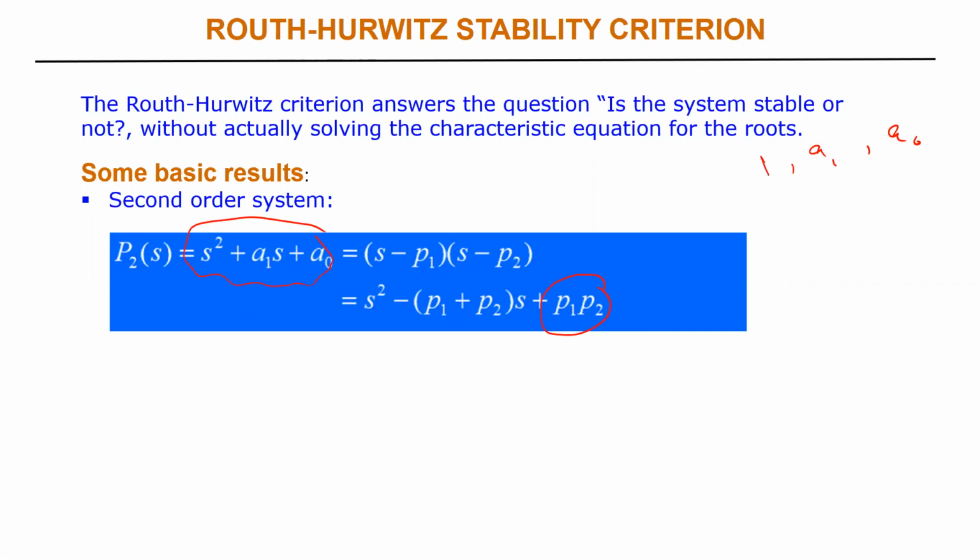It's an equation, so if they are negative, multiply everything by -1, and it will be positive. There will be no sign change. Or at least it is necessary that there shouldn't be a sign change for the poles to be in the left half plane. If there is one sign change, then definitely one of the poles is going to be in the right half plane.